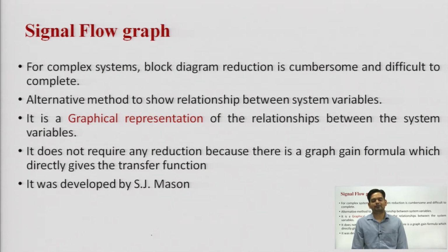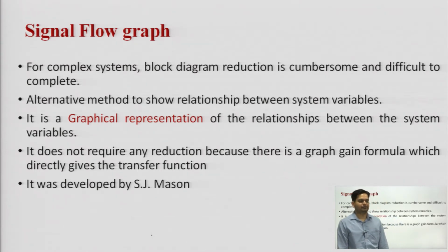So, in the previous example we had seen that we were dealing with G1, G2, G3 and G4. Suppose we have 100 or 200 blocks. In that case, applying the 8 rules to reduce and simplify them would be very complex, right. So, to simplify the calculation of transfer function, we go for SFG, that is signal flow graph, right. So, this is a graphical system, and we can say it is the alternate way for block diagram reduction for calculation of transfer function, right.